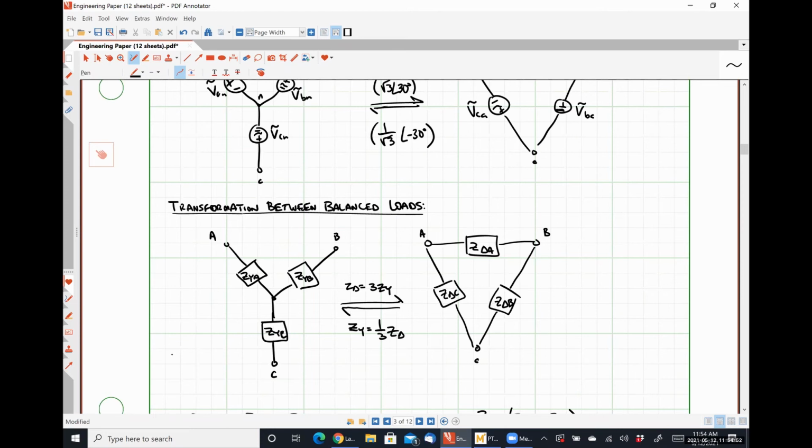So what we typically do is connect the fan blower motor to phase A and the fan intake motor to phase B on one building, then B to C on the next building, and then C to A on the next building, so that every 3 buildings everything balances out. Then we just repeat that over and over so that the total imbalance is very small, because we've designed it that way. If we hooked all of the intake motors to phase A and all of the blower motors to phase B, we'd wind up with a very large imbalance that would mess with things. So in practice, with reasonably good design, everything pretty close to balances out.